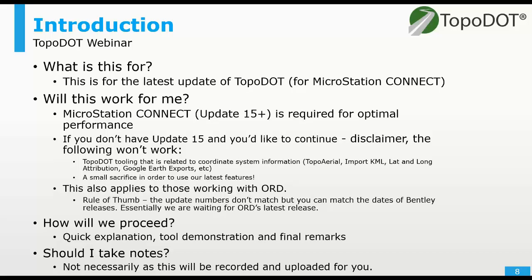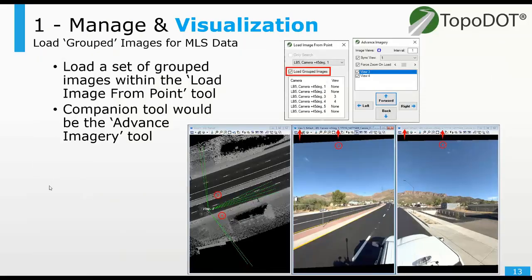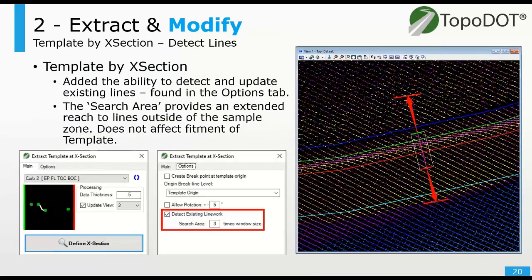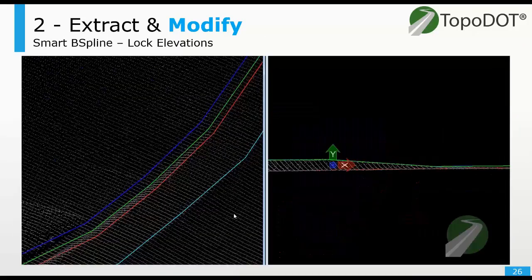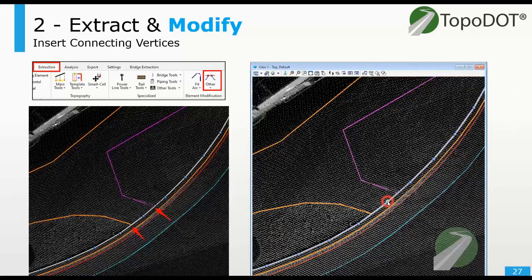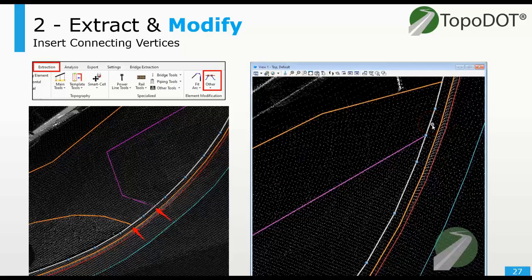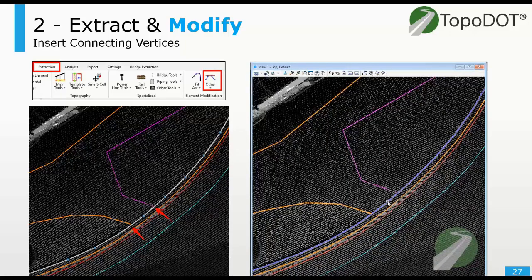Another question we should have here is about the insert nodes at the overlapping lines tool. The lines need to be touching in order for that tool to work. Otherwise, it won't place an additional node there. But if the lines are not touching right away, then you can use a drape to intersect tool. Or you could just move that endpoint to the line if it's not working. And you can do this globally too. Mike was showing a version of the tool on a few lines, but you can run it on multiple lines at the same time, not just a few lines. So if you have a large project, you can do that.